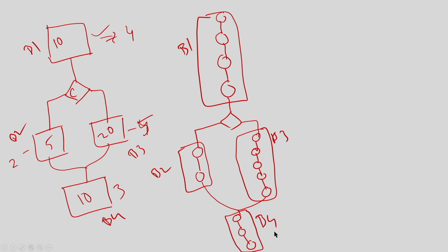I did all these basic blocks, meaning sequences of operations where there is no control flow. I take one basic block at a time, do the best scheduling to solve the problem, and then combine each basic block into this control structure, and this is my final controller FSM. This is what we have done. Then we know what operations are happening in every state, and based on that we construct the data path. That is the way we have discussed so far.